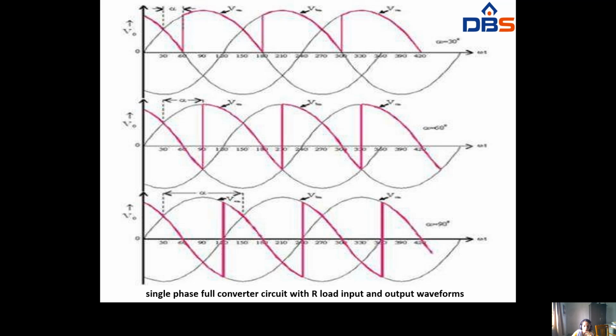So in full wave the voltage will be in continuous mode and the current also will be in continuous mode. Okay, so these are the waveforms for R load, the input and output waveforms for the single phase full wave circuit with R load.